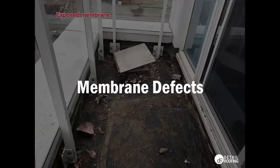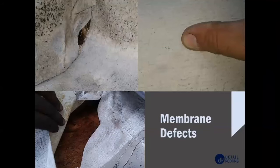Membrane defects. Very similar to any of the other roof surfaces throughout the building, there can of course be membrane defects for a variety of reasons. One of the things that we see very commonly is if there is a patio surface, a balcony, a terrace that has a single ply membrane that is not covered by any sort of protective roof system, we do see a number of defects and leaks in these areas, again, because of the higher foot traffic and just more objects on these surfaces.